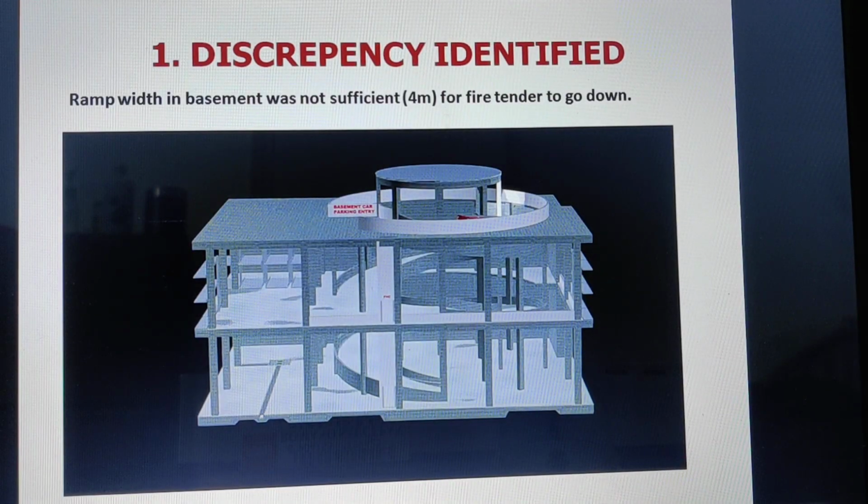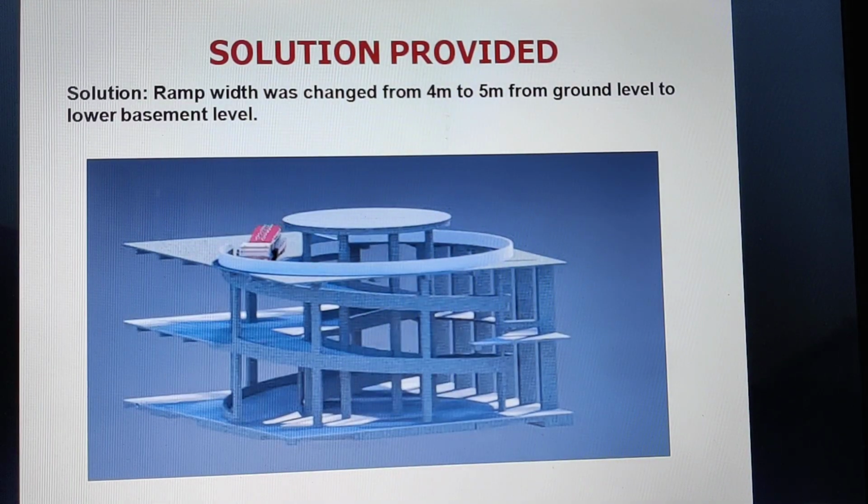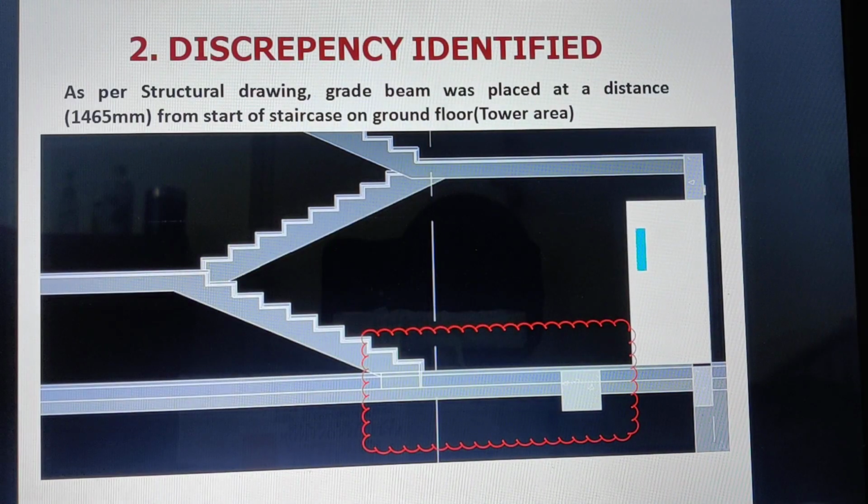This is one where ramp width in the basement was not sufficient. It was considered 4 meter and fire tender could not go down, and then when this came into the knowledge, then the solution was provided. It was increased from 4 to 5 meter.